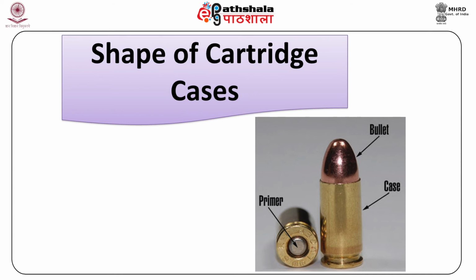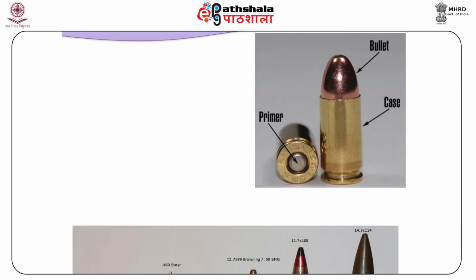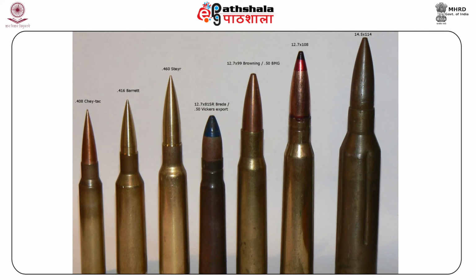It has been observed that if there is an abrupt junction of the neck and the case, the rounds develop greater pressure for the same quantity of powder. The combustion is more uniform. It appears that the abrupt neck joint deflects the hot gases inward.